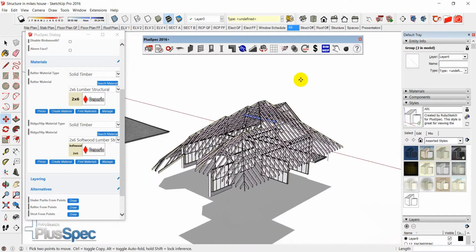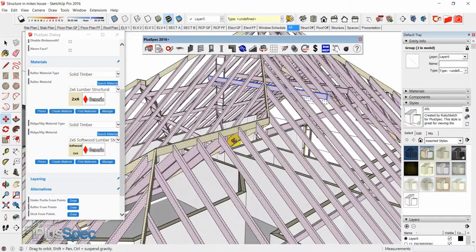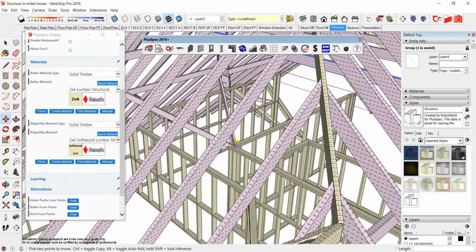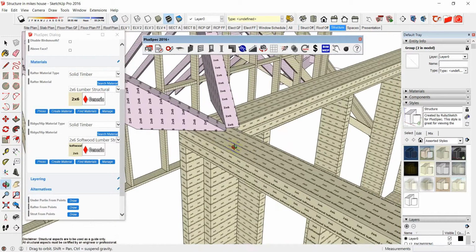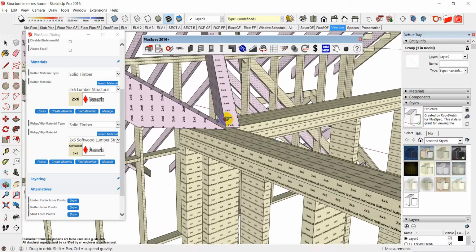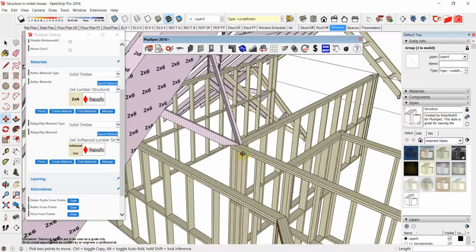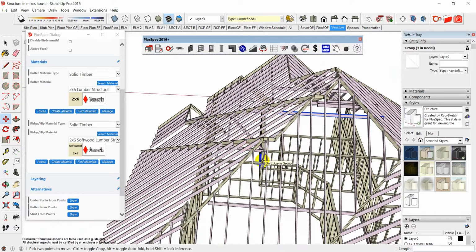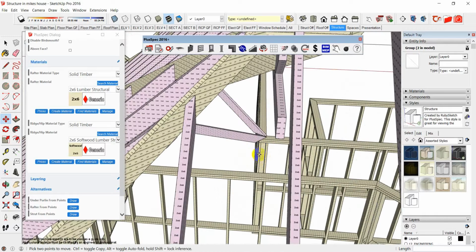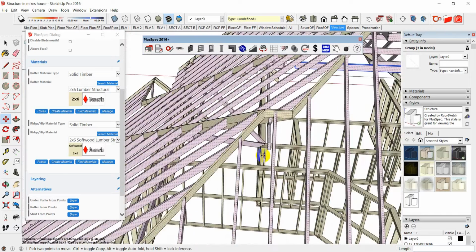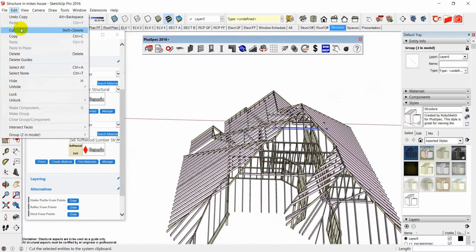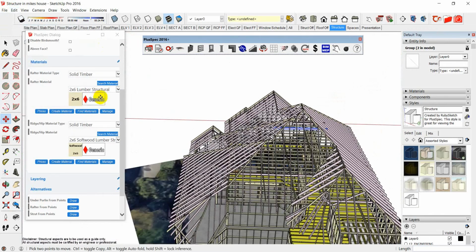The house itself, I mentioned before we had point loads, so let's go to our structure here. And here I have a point load where I've put some struts on, and I can probably move those around a touch. And what I want to do is make sure that that point load is actually going to follow through the house, so I can follow the load path. Because if this wall is not sitting over top of a structural member, basically all I'm going to do is bend the floor. So I'm just going to go here, edit, unhide, all.